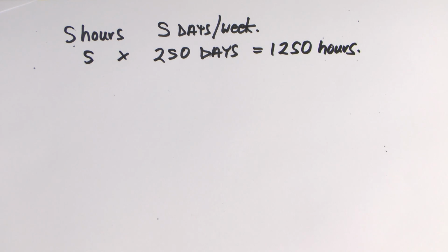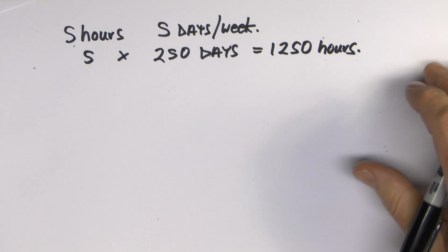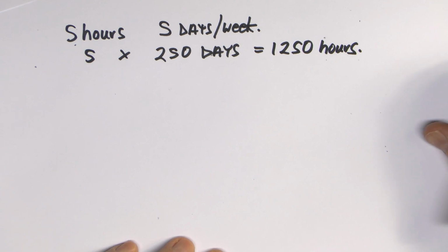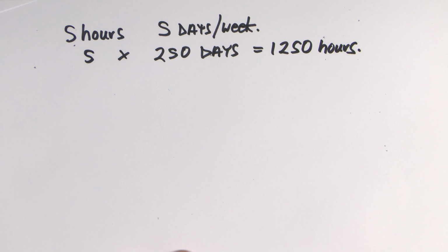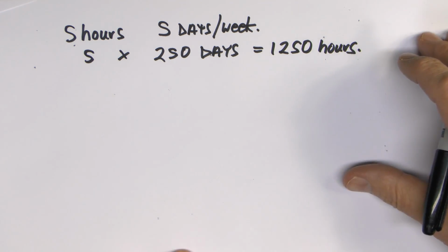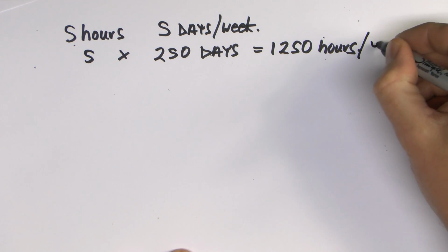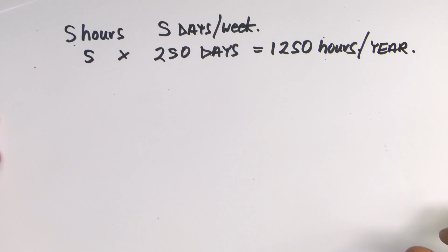of charging use. And again, we'll assume that it's going to be at the full 32 amps, although in reality it could obviously reduce that depending on the type of charger you've got and various other factors. But again, just to make it simple, so 5 hours charging each day, 5 days of the week, 50 weeks a year. They go on holiday for the other 2 and don't use the car. So 5 times 250, 1250 hours per year of current being used.